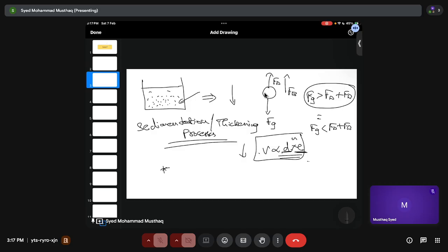They are dense particles. For them to settle fast, what if they get attached to each other? You can call it agglomeration. Then your effective size is increased, and so your settling velocity will also increase.